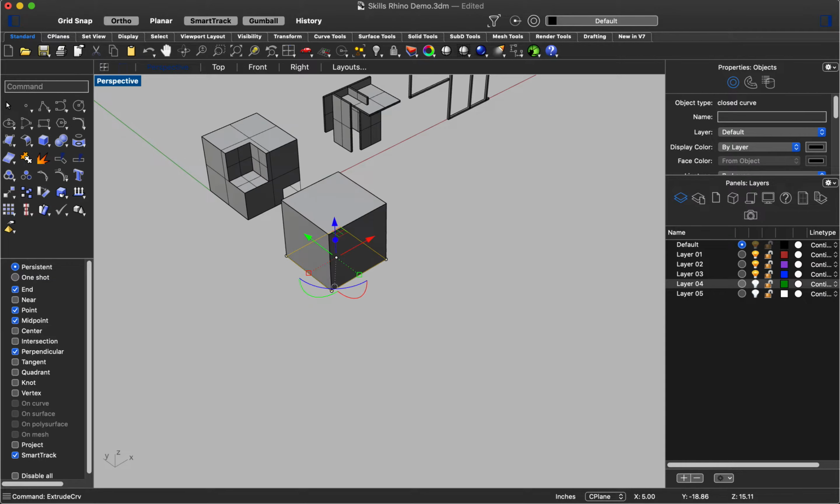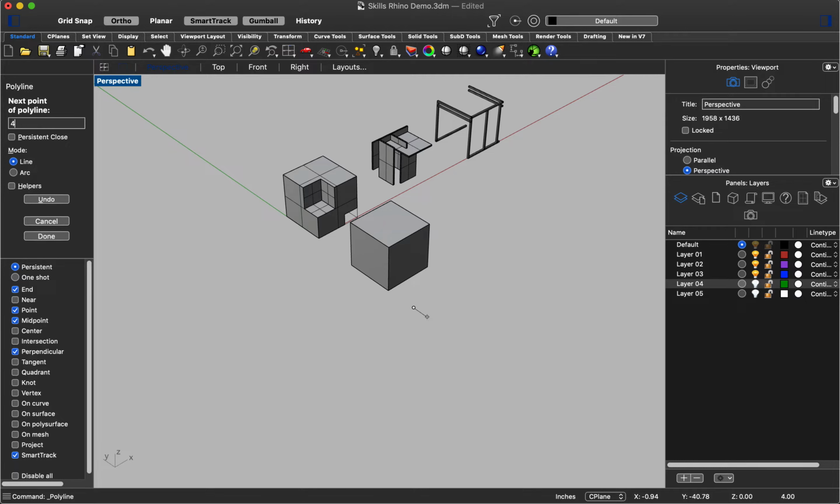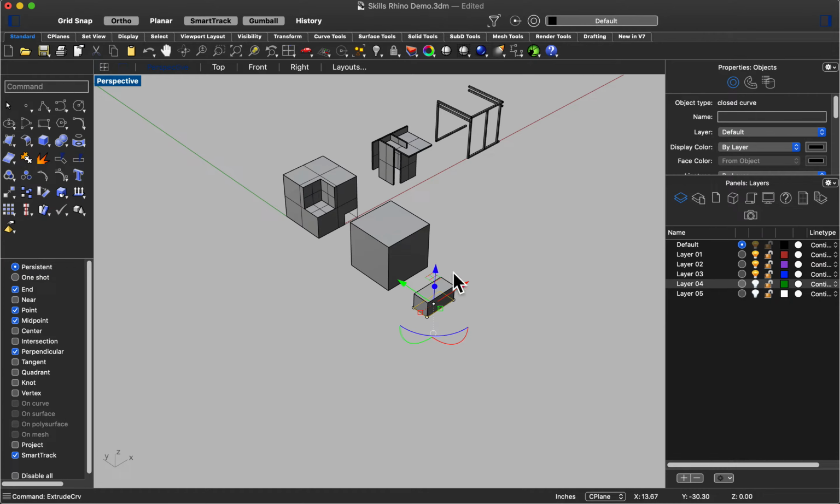And then in this case, my volume cube had this nugget here that was subtracted out of it, so I modeled that by, let's do something a little different. Let's say it's a 4-inch cube, so 4 inches that way, 8 inches that way, and then I'm going to complete that, type extrude curve, and extrude that, let's say another 4 inches.